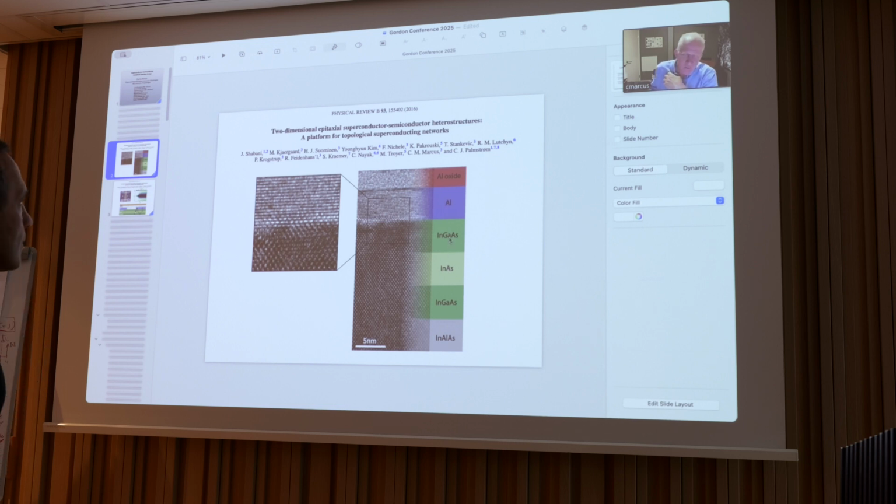It's a region of semiconductor with a slightly higher band gap that confines to some extent the wave function within this region in the Z, the growth direction, but still allows the tail to penetrate. It's only a slightly higher band gap, whereas if it was an oxide or something where it was impenetrable, then it would shut off the aluminum from the indium arsenide.